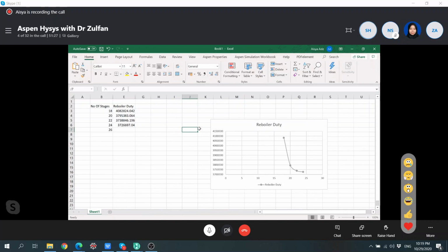It's cooling water, nothing compared to the reboiler duty. Because you are having this at about 160, 170 degrees C, we need 7-8 bar of steam. So we need to pay to make that steam. That is the OPEX.